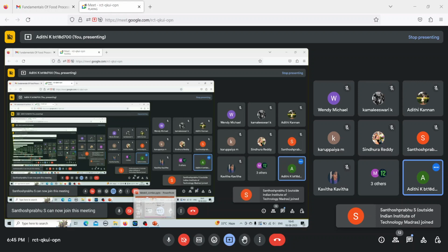Instead of going for a normal evaporator as we discussed before, one of the advantages of using an agitated thin film evaporator is, as the name suggests, you have an agitator or some kind of instrument to provide agitation or some kind of movement inside the evaporator. When you have a high viscous fluid, the heat transfer coefficient will drastically drop. That is, the high viscous fluid will provide a lot of resistance to heat transfer. It is easier to heat water than it is to heat honey or something very viscous.